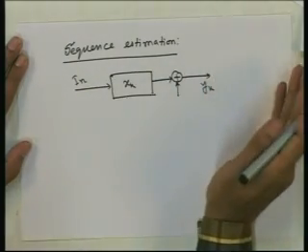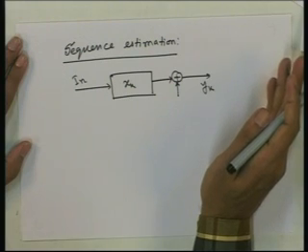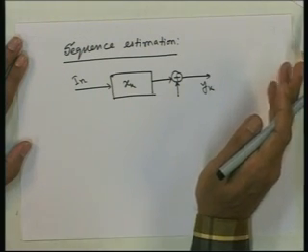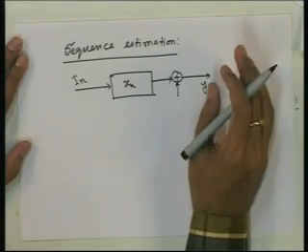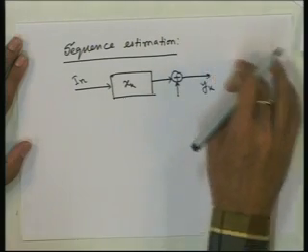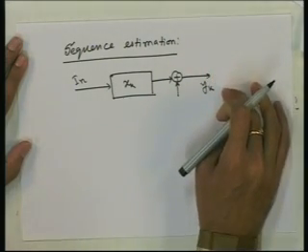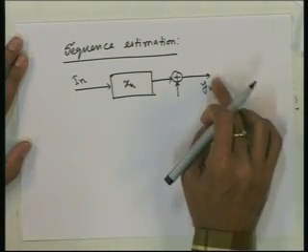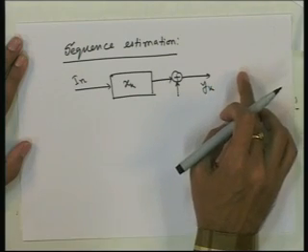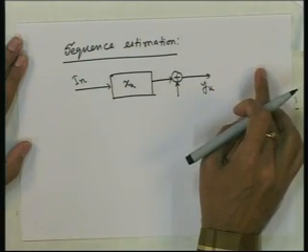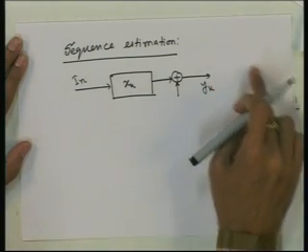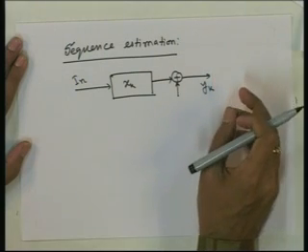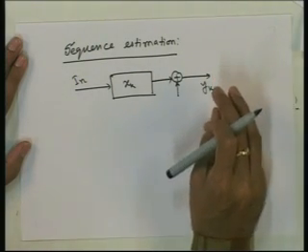And in the equalizer design, we have considered a simple structure for the processing we do after this, and that is, we said we will either use a linear filter here and then do quantization, or we will have a decision feedback equalizer, which is again done by implementing two filters.